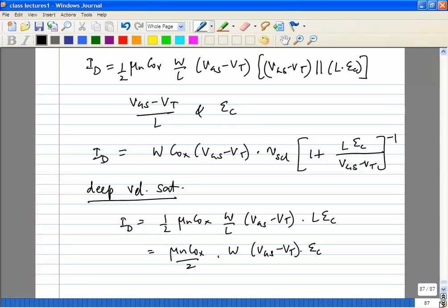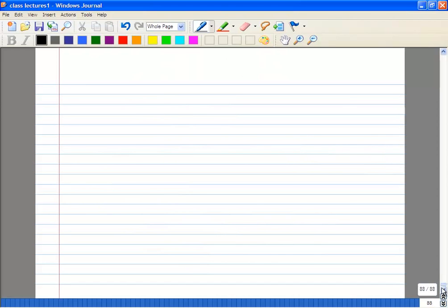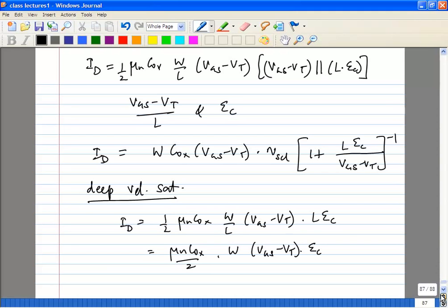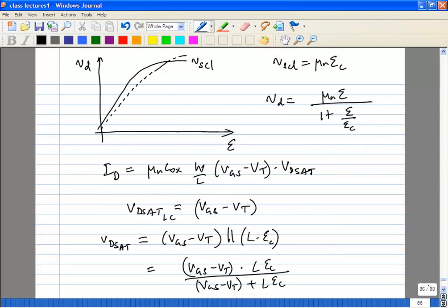Okay, so now let's look at the... No, EC is actually a constant value. It's E which depends, right? Not EC. Remember, we define EC as, so you have a scattering limited velocity. EC is related to scattering limited velocity by this equation. So EC is actually a specific value. Typically it could be some value, I think I have it in the notes. It's somewhere around 1.5 times 10 to the power 6 volts per meter.